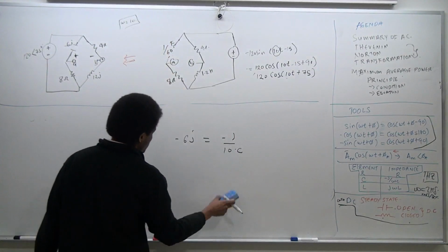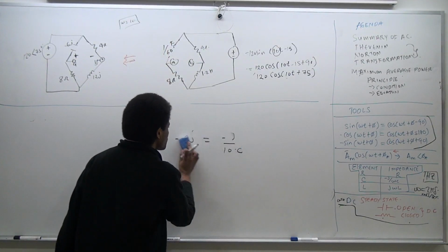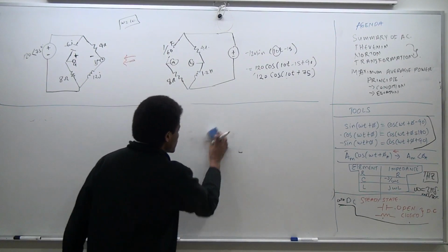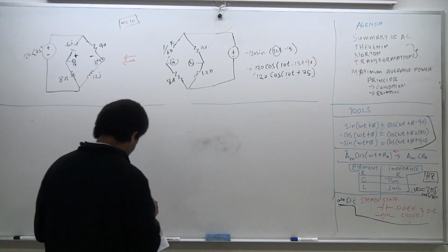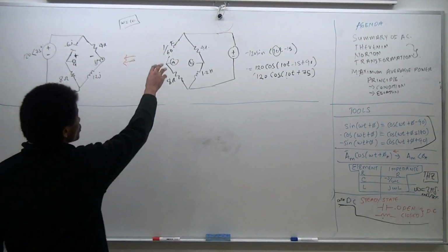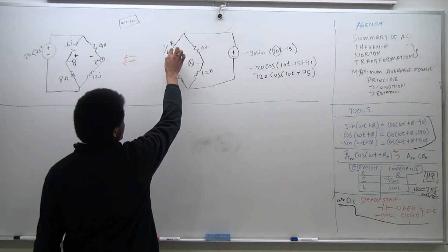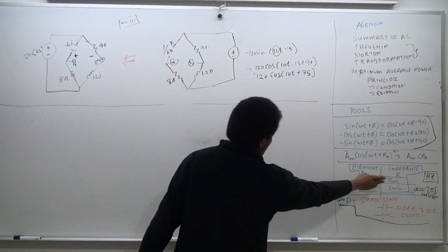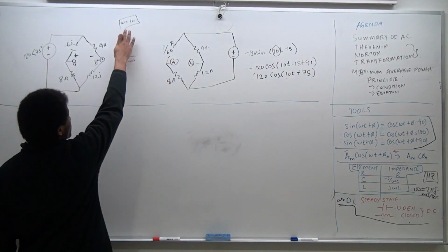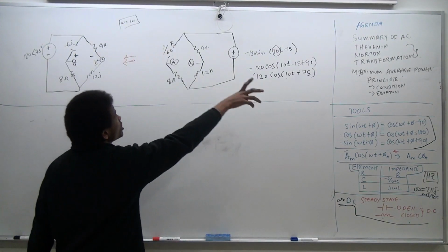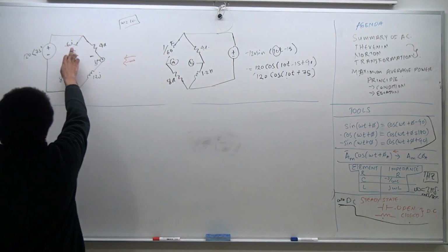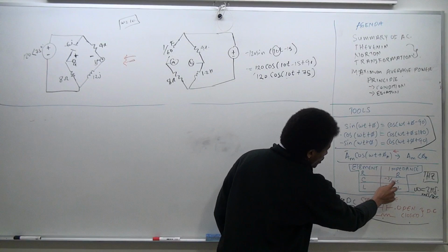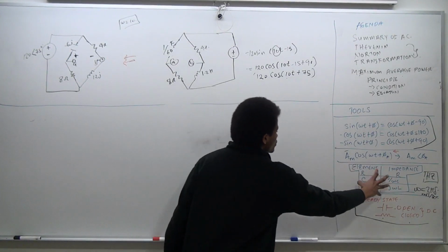So we're given this problem. We have a capacitance of 1 over 60 farads, which is some value. We multiply it by the angular operating frequency, measured in radians per second, find the reciprocal, and you indeed find negative 6j. There's a negative that comes from the top, so you get negative j over omega C. Once you commit this to memory, everything becomes easy.